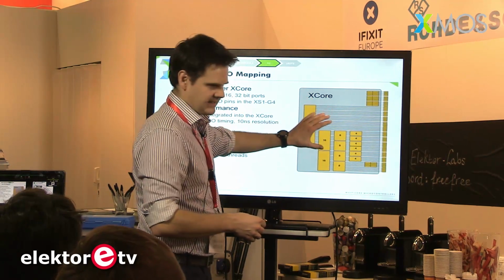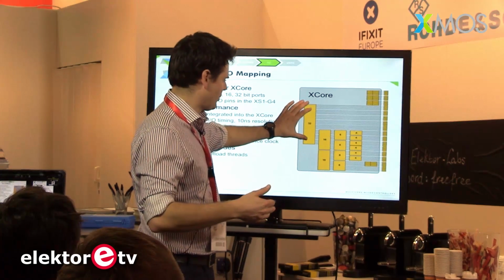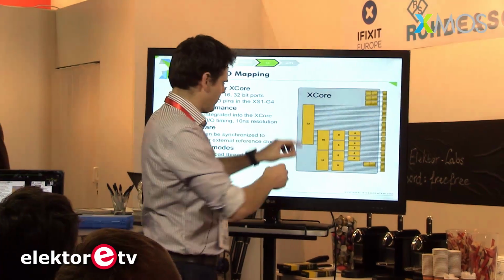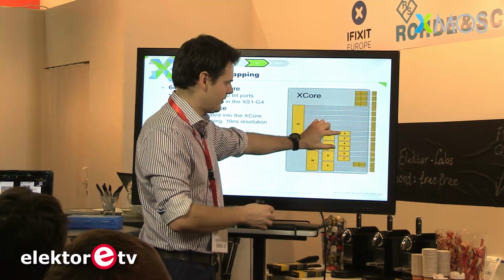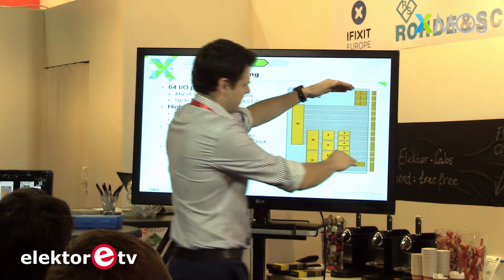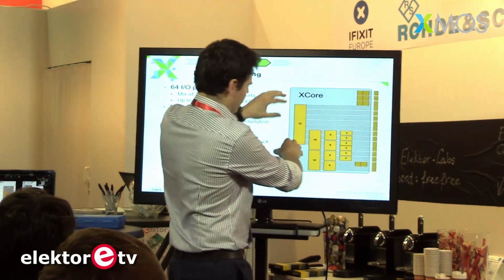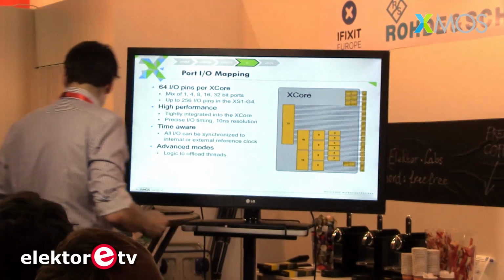And this diagram is set out to show you that if you interface to these ports in 32-bit mode, it's actually going to use these ports here. So you can't then also interface using these 4-bit ports. So this is the number of ports you have, and how you interact with them depends on what's suitable for your code.